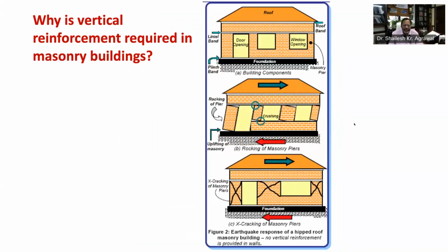When the ground shakes, the inertia force causes the small sized masonry wall piers to disconnect from the masonry above and below, as shown in this figure 2b. These masonry subunits rock back and forth, developing contacts only at the opposite diagonals. The rocking of these masonry piers can crush the masonry at the corners.